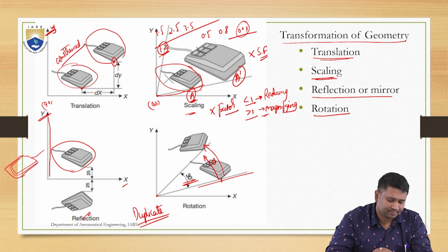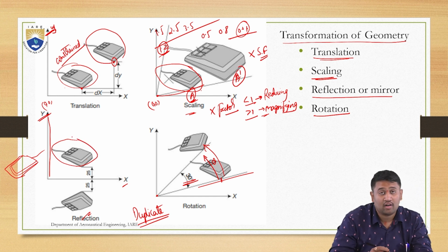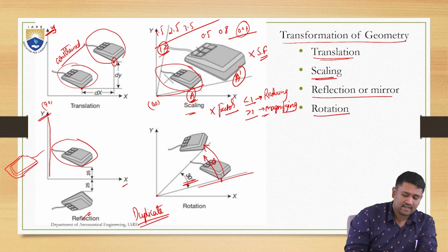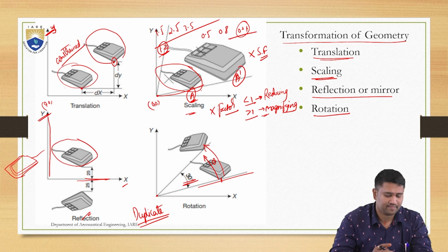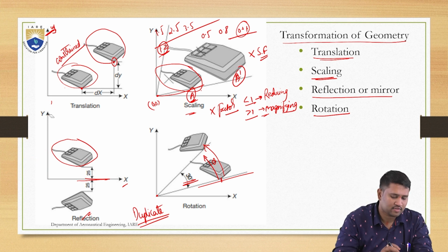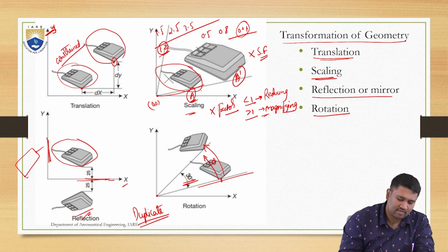While for reflection, we are supposed to select a model, right? Or the face, anything you want to reflect, you can select, and then you select an axis through which it is supposed to get reflected, right? In this case, if I select my y as my reflecting line, the model gets formed here, right? If I take my x, this is the model that is being formed.